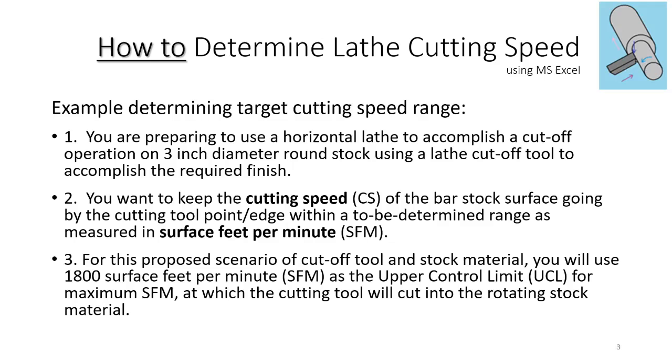So if you imagine the bar stock as it goes by, the tool sees a tangent right there, and whether it is a real tight radius or large isn't too important. On the tool point, it's down at a very small fraction of an inch, not quite molecular, but somewhere in that kind of range.